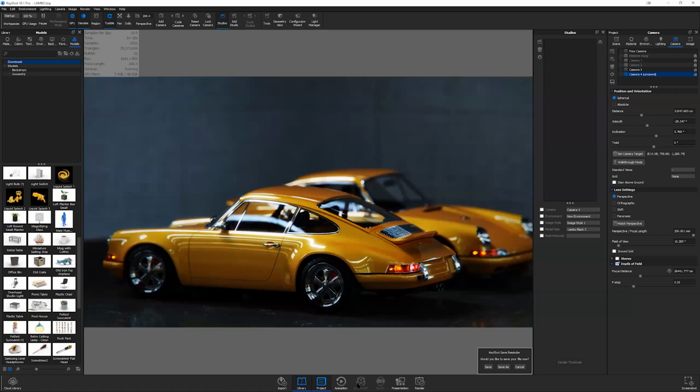A couple different questions around color and color management. How do you handle that for print, in terms of getting CMYK output from KeyShot over into the print side of things, making sure that that is consistent? So we typically output in RGB from KeyShot, because especially early stage, we'll make sure that everything is aligned, and it's in Photoshop where we'll try and correct it.